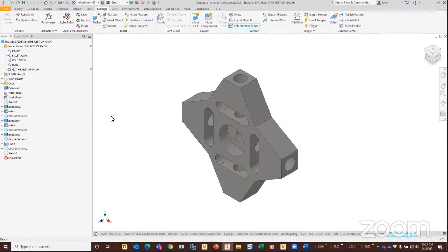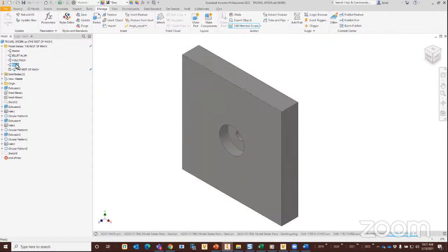I think it should be really helpful. The other way to activate that besides this pull down is to click the top pen. Single click, we're set to factory scope. Click again, we're set to member scope. And of course, if you double click on a member, you're now editing just that one member.